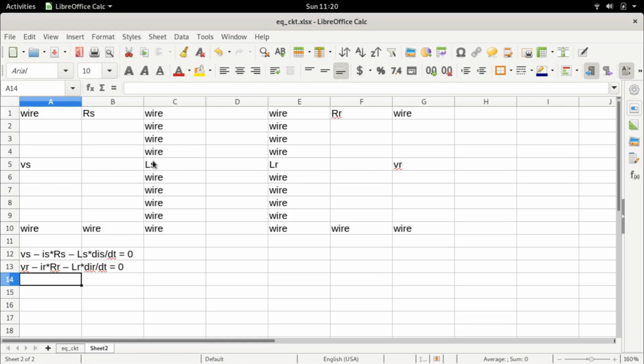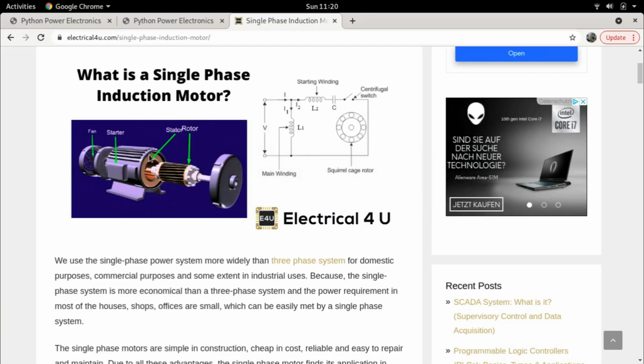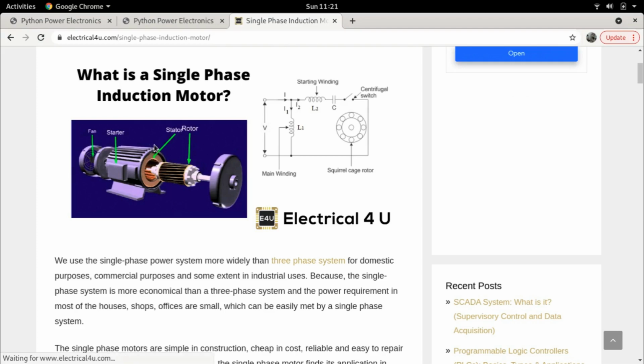As we already said before, not all of this current flowing through the inductance will produce a flux that links in the air gap. Let me go back to the circuit here. The current flowing through the stator windings will produce two types of fluxes. There will be fluxes which leak into the air outside. So these are not fluxes which actually go into the air gap. Therefore those fluxes which leak into the air do not do anything useful, but they are produced.